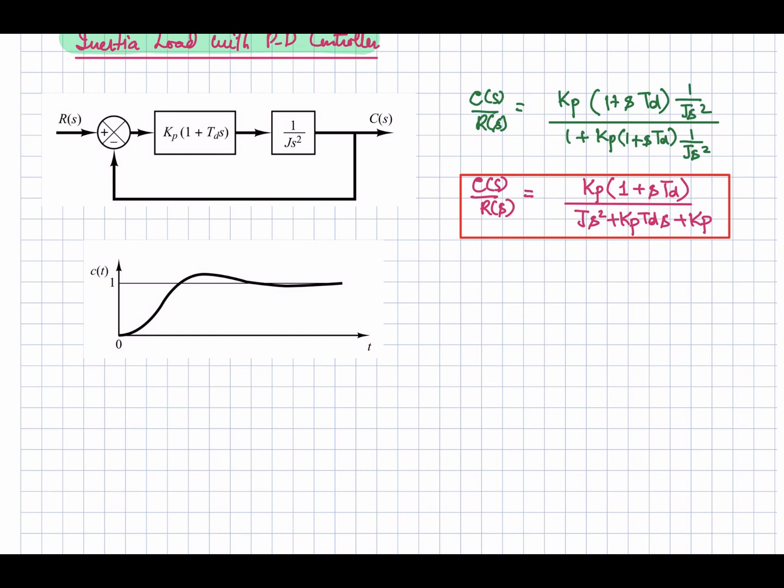Because the derivative control operates on the rate of change of actuating error and not the actuating error itself, this mode is never used alone. It is used with the proportional action. So it is always used in combination with the proportional or proportional plus integral control action, right?